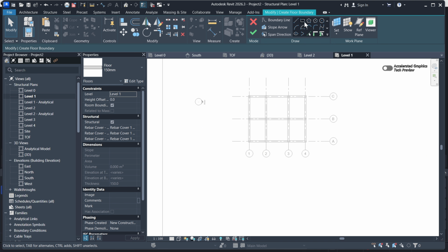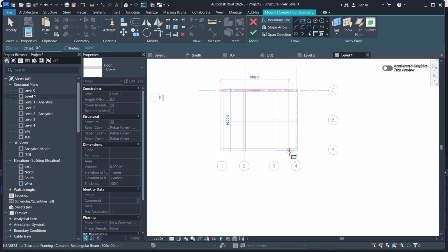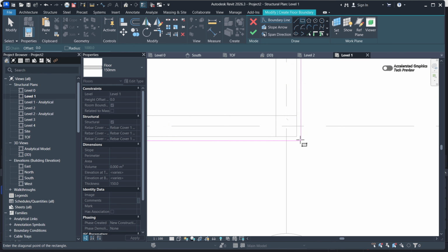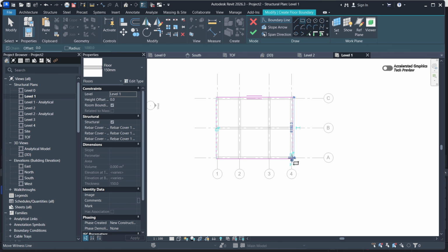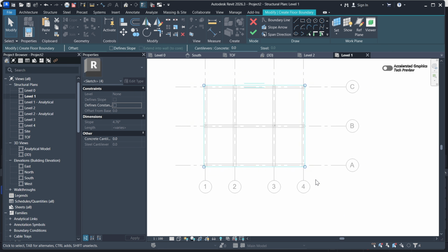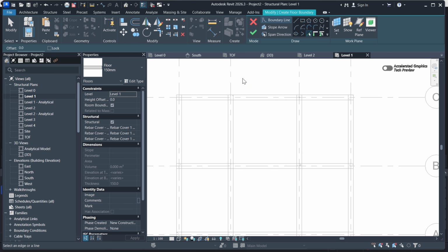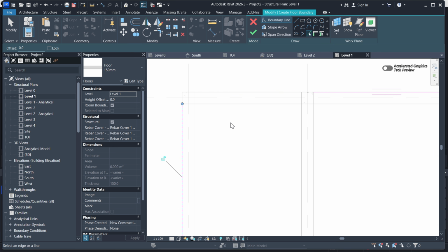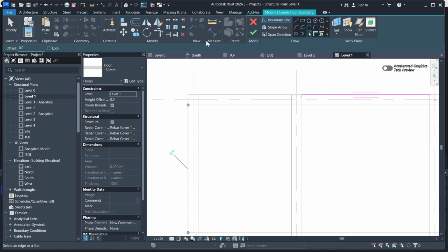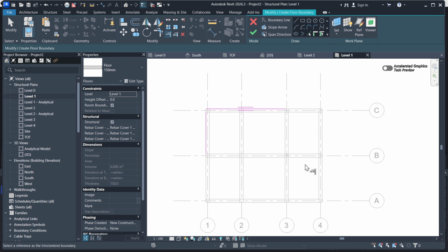What I want to use is to just use a rectangle and just click. It becomes easier because I can just click, because this is rectangular, or if it's a square, and just click that point and you have it like that. And another option could be, let me select everything, those magenta lines, and delete. Another option could just be to use pick lines, so that you just pick the edges. You can pick this edge, you can pick that edge, and now type TR on your keyboard to trim, or you can click trim from there, click there, and you can trim the edges. So just pick all those edges and trim.